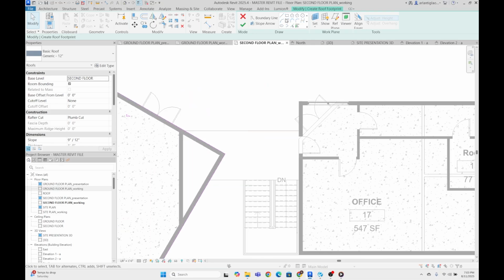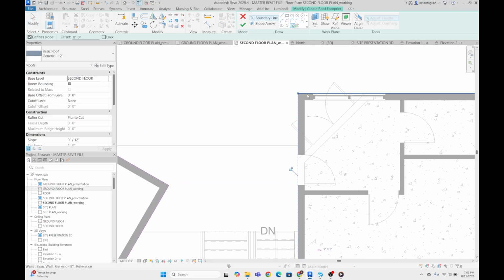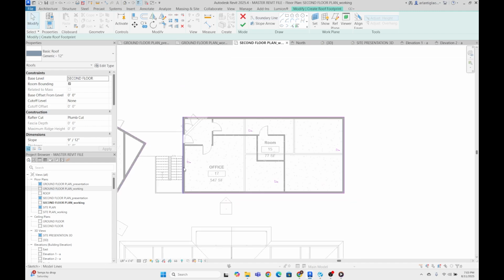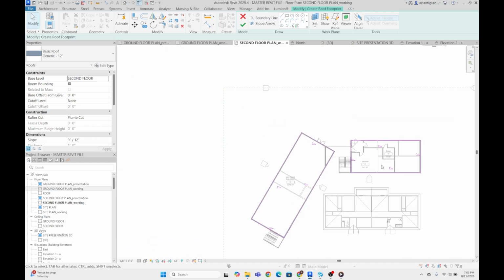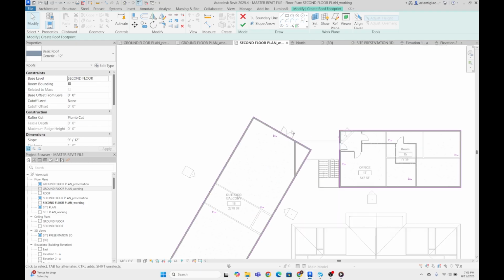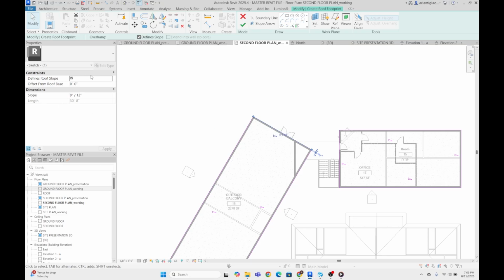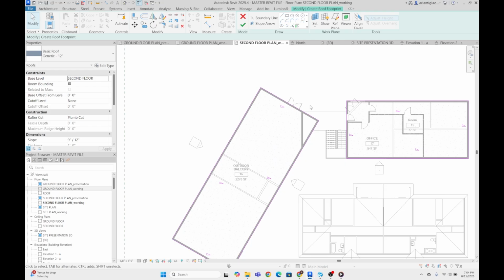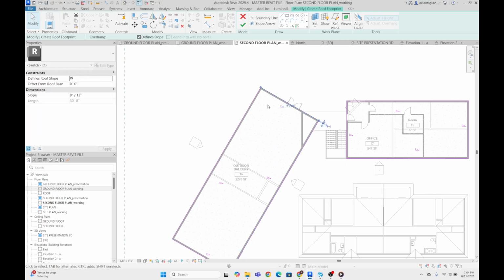And go over the outline of this part of my building as well. I have these two masses of roof created. If we click on the line here, we're given a couple options. One thing we want to pay attention to is this define roof button and also the slope setting here. I want my roof to be like a gable roof, so I don't want these lines here to define my slope.